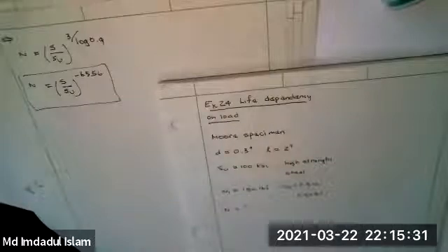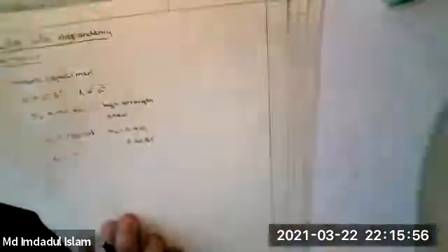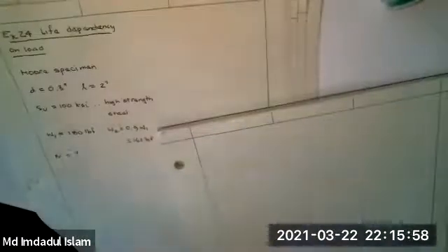Well, the basic approach here is we'll go calculate sigma max. And once we get sigma max, okay, for these different loads, that'll become the S, and that'll tell us which region we're in. So when you do these life estimates, you have to decide which of these formulas you're going to use, and there are three. You could be in any of three regions.